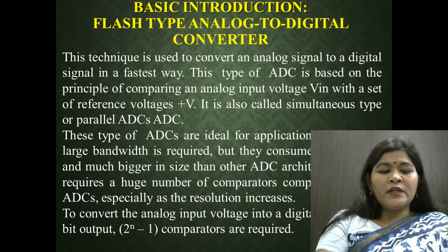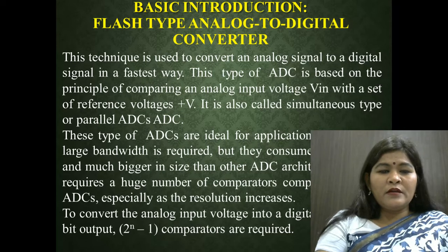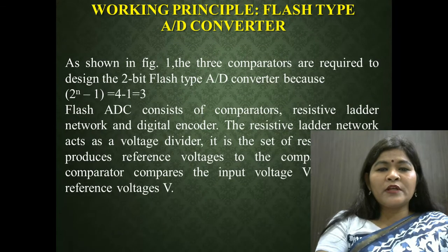So student, these flash type analog to digital converters are based on the principle of the comparator, but in the circuitry they require a large number of comparators, therefore the circuitry will be larger. So let's start with the working principle of this flash type A to D converter.